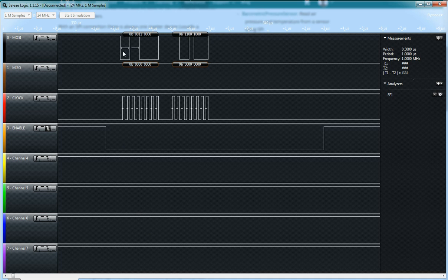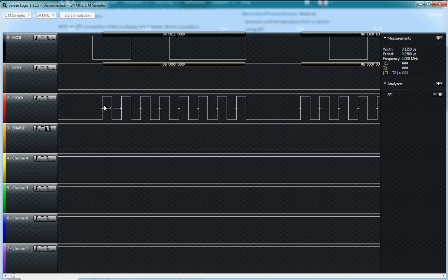So in this case, we have the clock signal, and in this particular case, the chip will listen to whatever the MOSI line is on the rising edge. So you can see these arrows as the clock is rising from 0 to 1. It will listen to whatever this signal is. So when this clock rises, this is a 0, so the first number will be a 0. And as it rises again, it is still a 0, so the second number will be 0. As it rises for the third time, this line has actually risen up to a logic level 1, so it reads it as a 1, and so on and so forth. Again, in part 2, we'll cover the practical examples of this and what all this means.